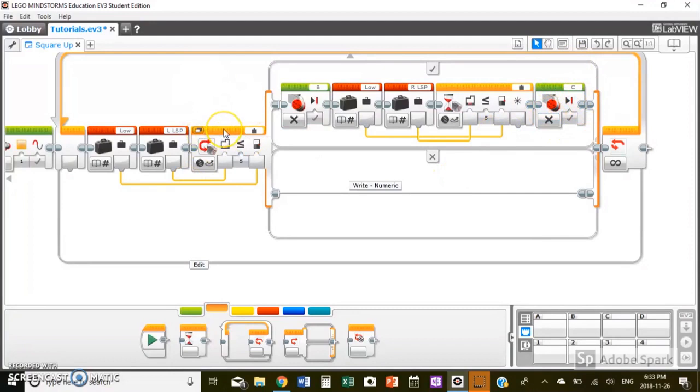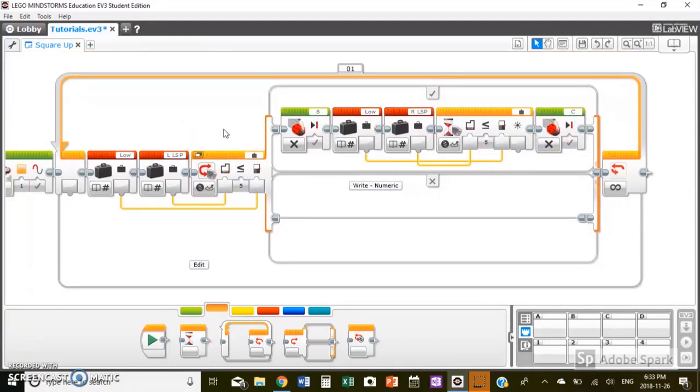So all this chunk of code does is initialize the variables at the beginning, of course. It's sending off a signal for debugging here with the orange light. And now for the loop part, it's checking if the left light sensor port has seen less than or equal to the low light value.